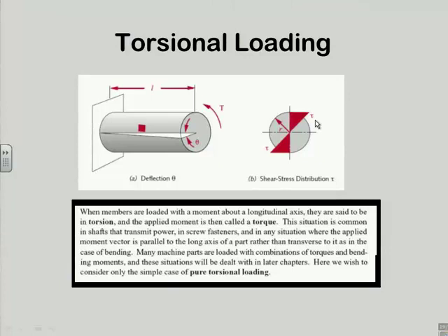Imagine this is a bunch of Necco wafers, right? And now I grab one end and the other, and I twist the stack of Necco wafers, just holding onto the two end ones. What's happening? They're all sliding on one another, aren't they? That's my torsional shear, okay? Just like this is shear due to bending, that's torsional shear. I can have them both present at the same time. That's nothing against that, okay? So that's what we're talking about.